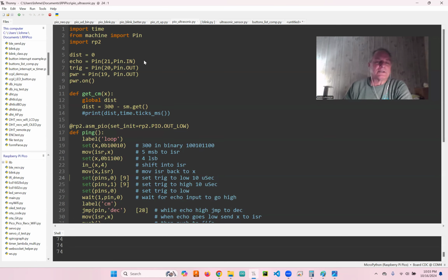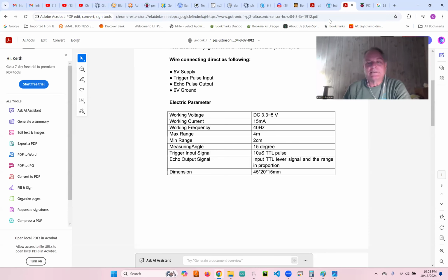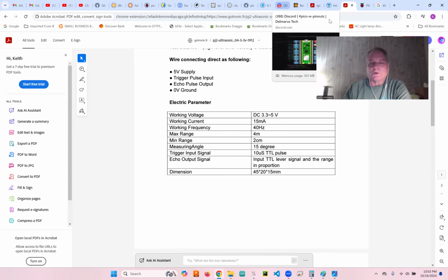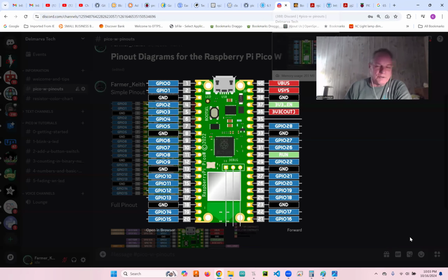And so let's look at the pins. A lot of times I'm lazy when I'm coding or wiring up things. So you've got the four pins on the sensor. From left to right, you've got VCC, then trigger, then echo, and then ground. I looked on the data sheet, and this thing only draws 15 milliamps. That's just about the top range of what you're supposed to draw on each one of your GPIO pins. But I said, I think it'll handle it.